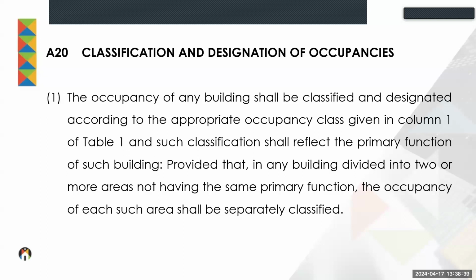Then it will be dual, and you will have to deal with each type of building with its main or its primary function. So there you might have to separately classify the different occupancies of the different types of buildings. Because the farming shed is not going to be an H4, it's going to be something to do with a store, etc., to deal with farms, whereas the house is going to be purely for dwelling purposes.